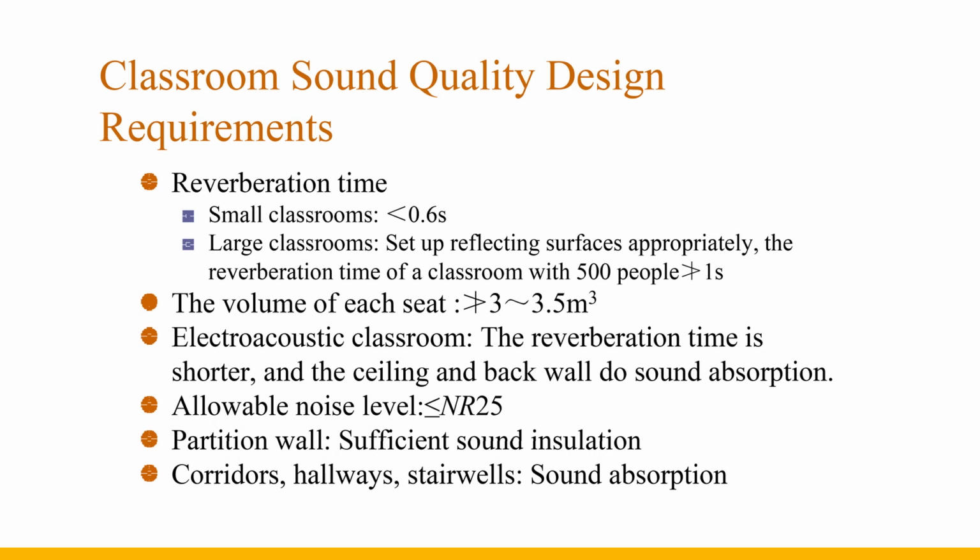The sound quality design requirements of classrooms are to ensure language intelligibility. Small classrooms should prevent the reverberation time from being too long, and it should be less than 0.6 seconds. Large classrooms should be properly set up with reflecting surfaces to make full use of the primary reflected sound to ensure sufficient sound level. The reverberation time of a classroom with 500 people should not exceed 1 second. The volume of each seat should not be greater than 3 to 3.5 cubic meters.